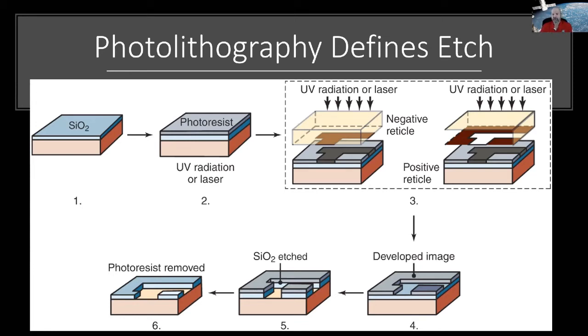There's dry etching, where you use a plasma etch, kind of like a blowtorch. Okay, it's a little more controlled than that. Or you can use wet etch processing. The wet processing can also remove whatever's exposed. So the photoresist acts as a blanket or a protection layer from the elements. And then wherever it's open, you can etch away.